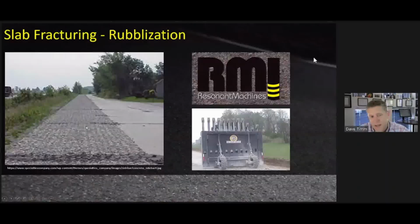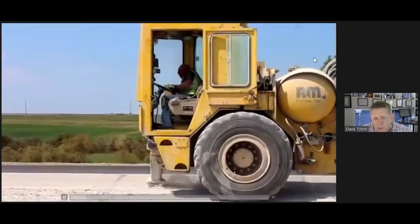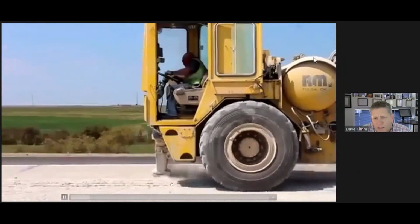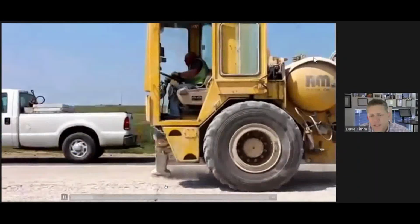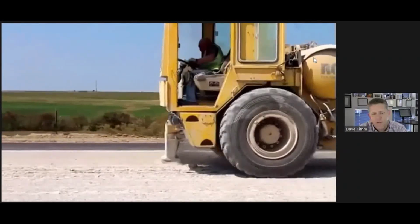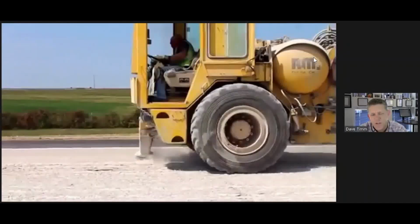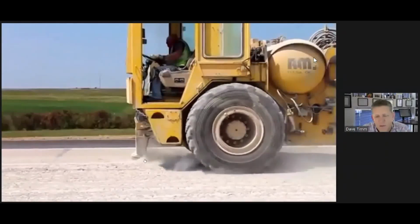Another approach is to rubblize the pavement. So rather than having short slabs, what we do here is basically rubblize it down into small chunks of broken concrete and aggregate and so on. There are a couple of approaches here. There's a resonant hammer, and I'll show a quick video of that. There we go. You see that high frequency, low impact. It's resonating at about 44 hertz. And as they're going along, it's literally shaking the slab apart. What's left over, once it's been recompacted, is really high quality base material over which we can pave.